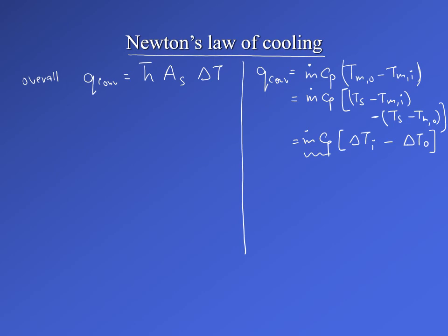Let's say we are working with constant surface temperature. For that case, and that is the main interesting thing, because if it's a constant heat flux, then we can simply calculate Q convection as the constant heat flux times the total surface area of the pipe. Okay, so this is for the constant surface temperature of the pipe. So we can replace m dot Cp from the expression that we obtained earlier. I will write it. So this is the logarithm. I did not show that in the slide, but that was an intermediate step when solving the differential equation for a constant surface temperature. Okay, so this is what we had earlier as an intermediate step.